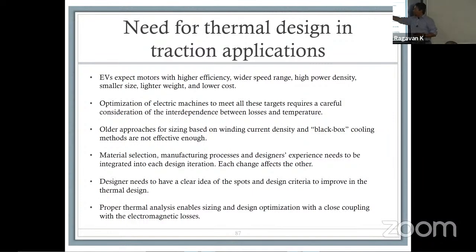So all of the optimization that you're talking about specifically has to have a mechanism that connects each one of these losses. You cannot just talk about one option and completely ignore the other. In some cases, with the switch reluctance machines, you will see that NVH radial forces are major, so that might be a primary objective function that you're trying to minimize. But you cannot ignore thermal behavior. So you have to start coupling them together in an overarching system.